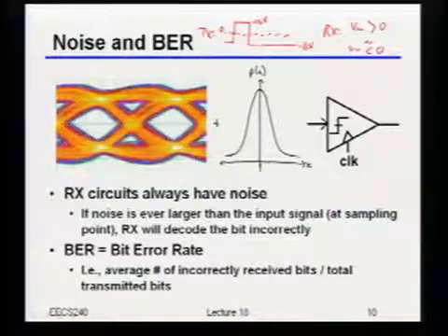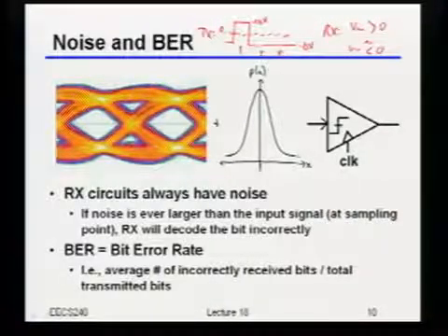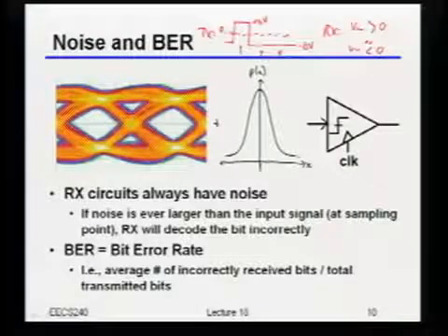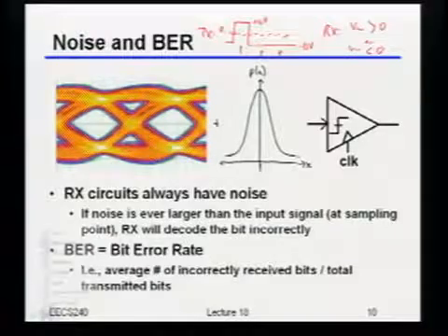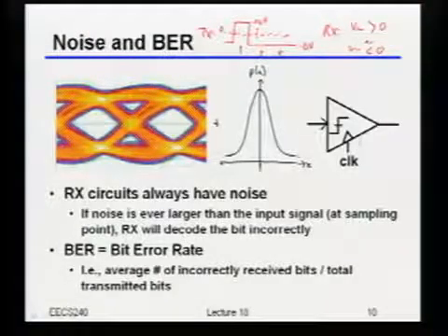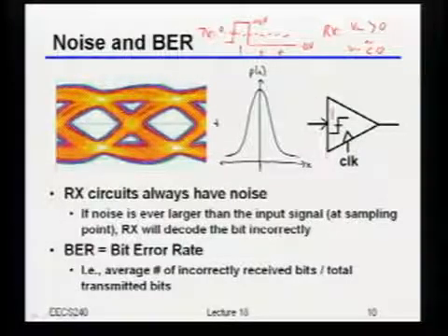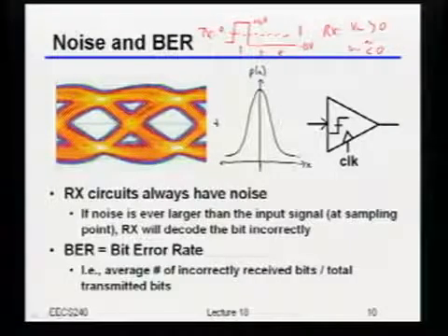Okay, and I'm probably going to do this at a particular point in time, as we had talked about before. So in other words, what my receiver really should just look like, at least in the simplest case, is basically just a comparator, where that comparator, in this case, has a so-called 0 threshold, or a 0 decision point, okay?